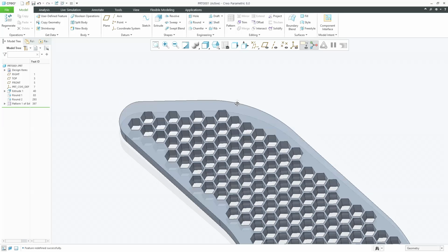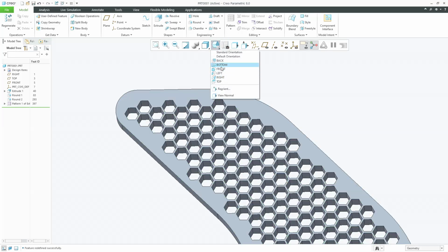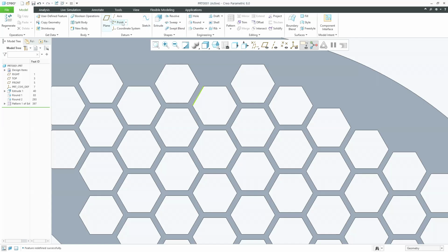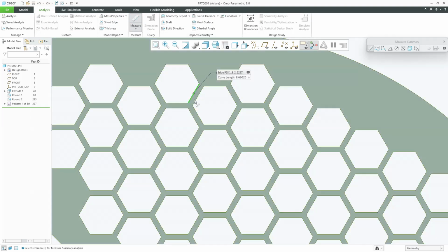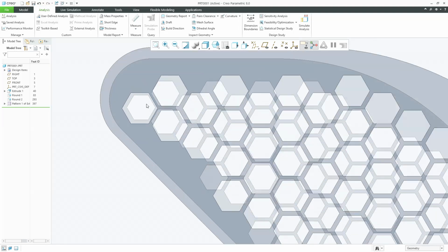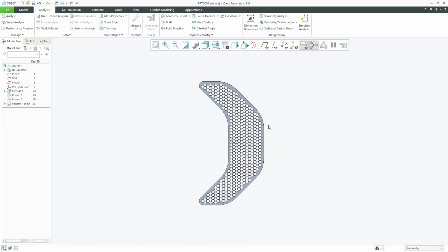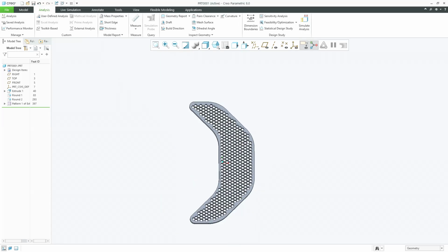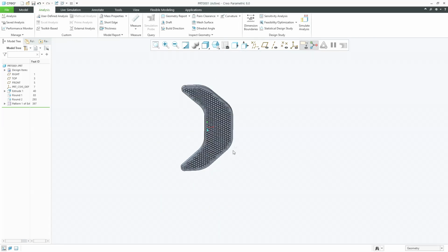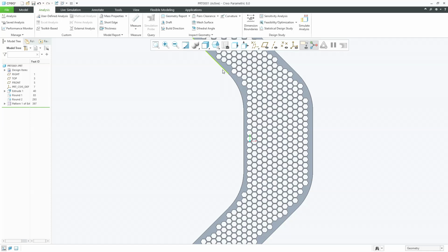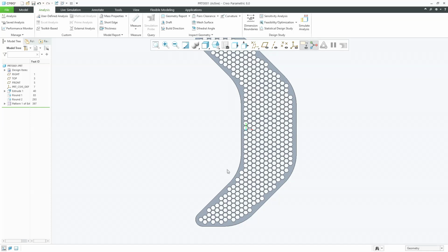Yeah. So once it is done, here you can see a honeycomb design pattern which is perfect. Let me move to the front view. The wall thickness between each and every hexagon will be 2 mm in total, 1 mm in half, and the hexagons have been patterned. As I mentioned, since we have given the border value as 15 mm, we can see the material applied here. Make sure there is sufficient material in all the corners. Please check the wall thickness at the minimal gap as well as at the maximum gap. Does it achieve your project's requirement?